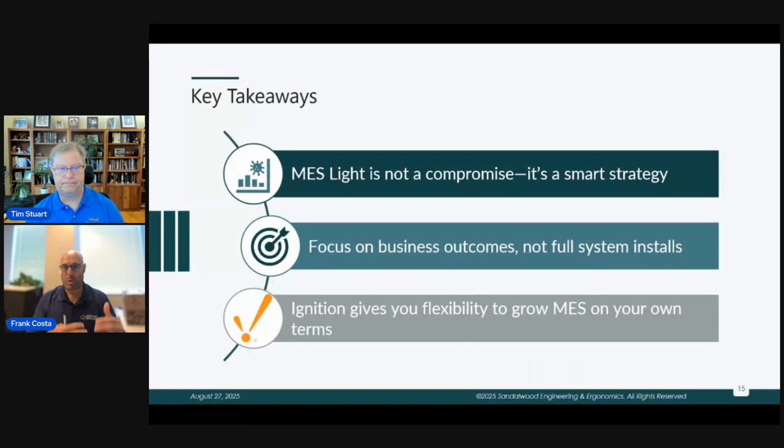Depending on the age of the equipment, I'm talking to someone right now where they've got a very old sensor that has to be connected to a PLC that isn't very, we'll call it reliable. They keep shutting power on and off. We're looking into, hey, how do I convert this to an IO-Link sensor, which inherently can send information to a PLC, and the masters blow out MQTT messages, which Ignition, as we talked about, can consume right away.